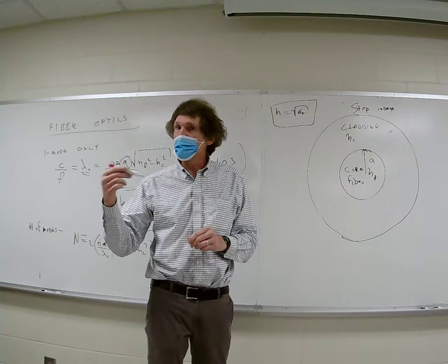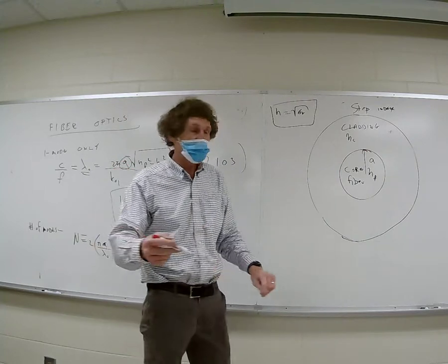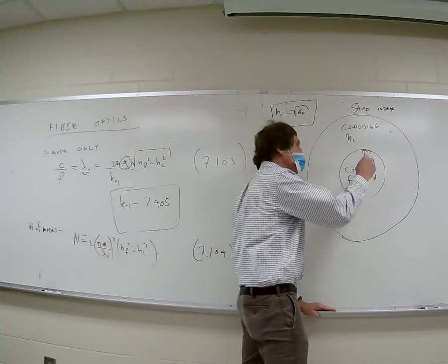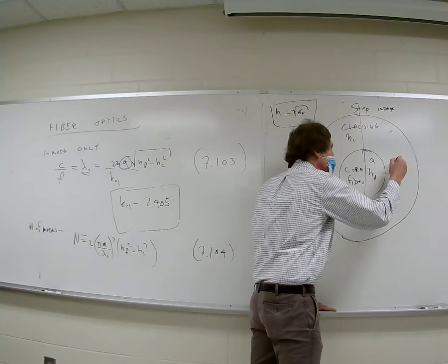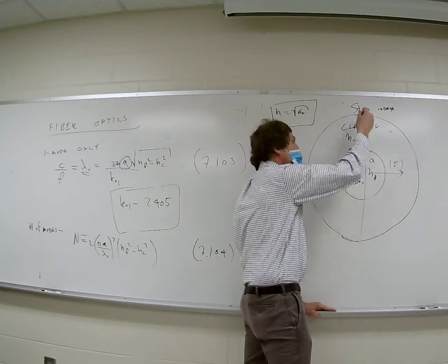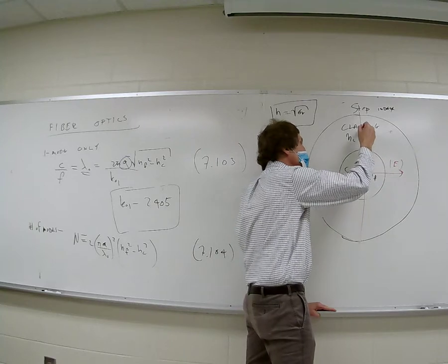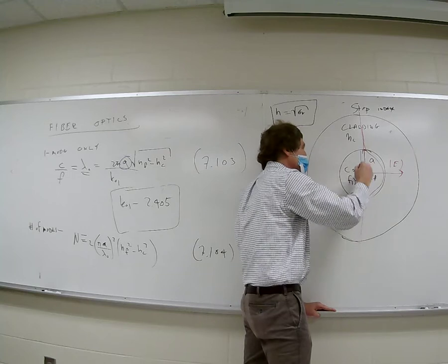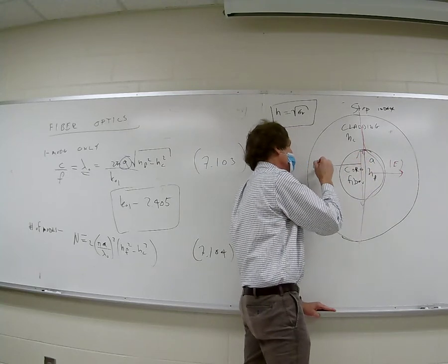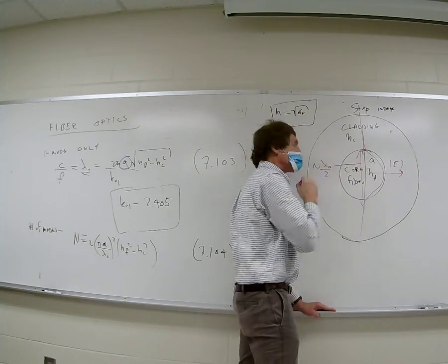If you go and you're an engineer and you've got to interact with people who are talking about fiber optics, well, they talk about the O mode. What they're really talking about is the magnitude of the electric field versus radial distance. They're talking about something that is 0 and then it goes up and down, and this is about lambda over 2.